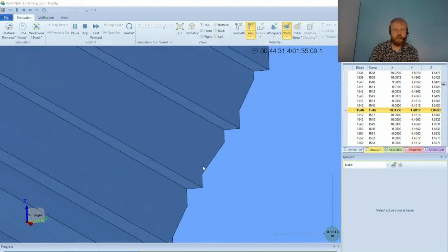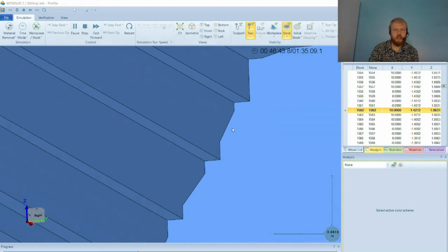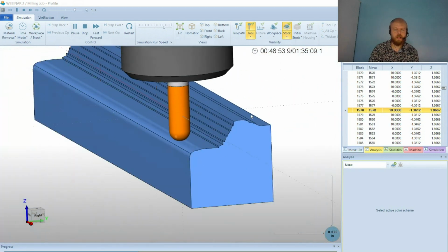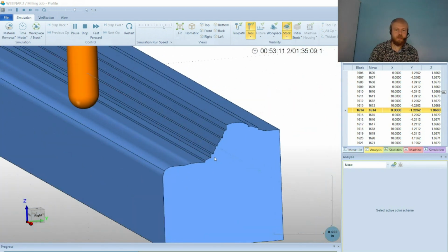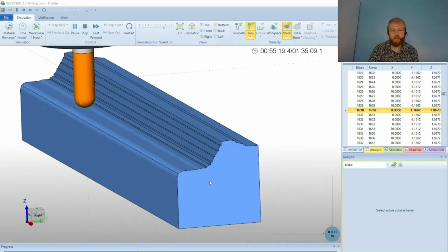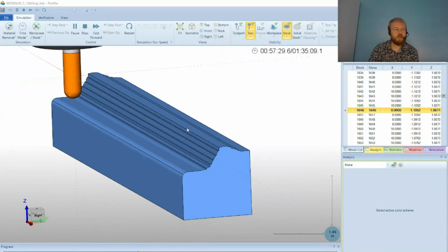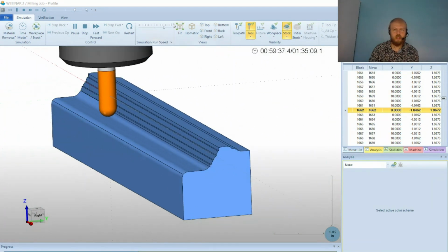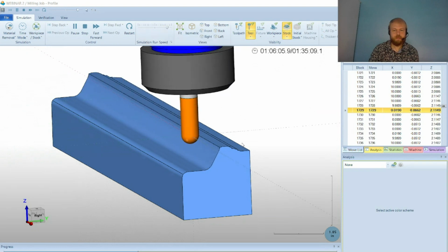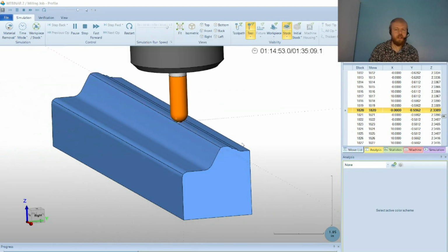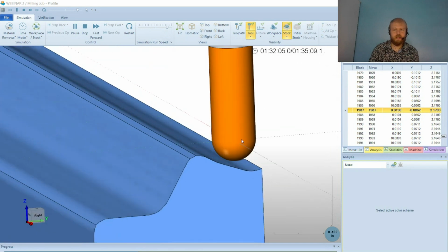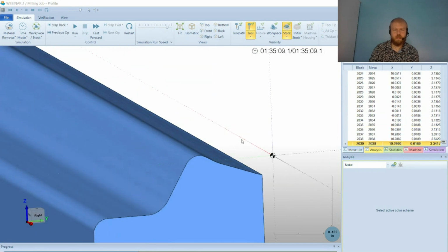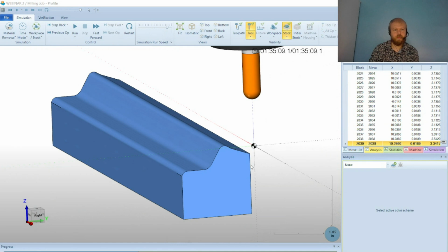You can see how much the intermediate steps remove so that the planar toolpath can come back and mill that out. Basically just 10 thou, maybe 15 or 20 thou remaining, so that there's not too much for the finish pass to clean up there. But yeah, the number of intermediate steps to do a couple of additional passes after our original depth of cut can be really useful there.